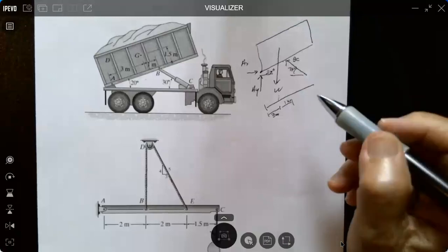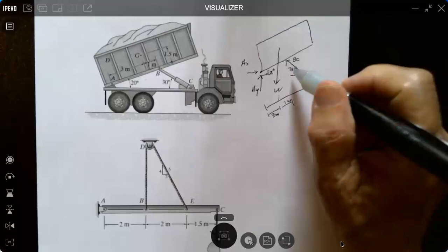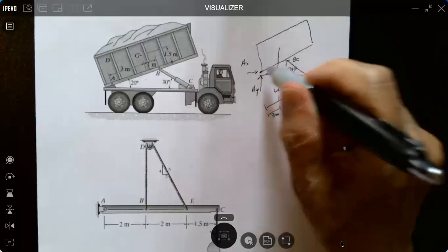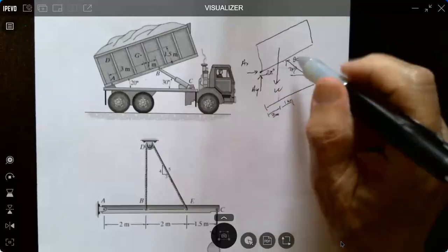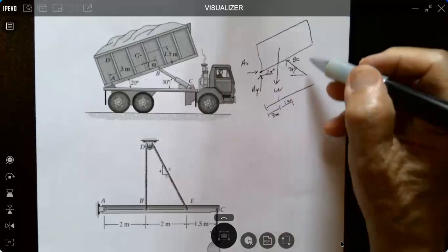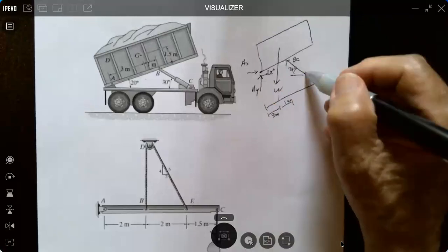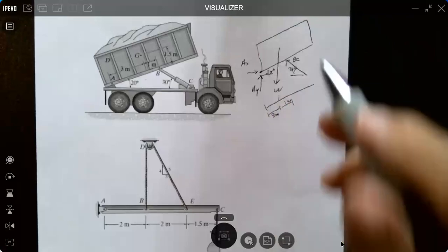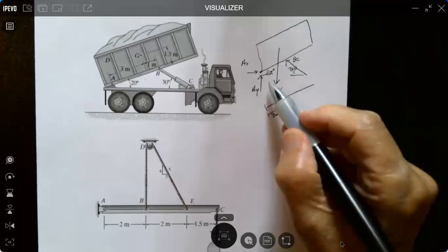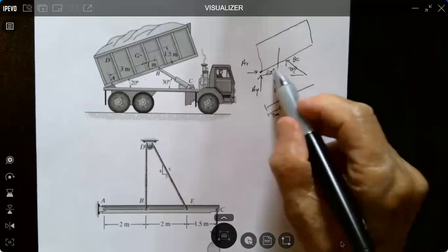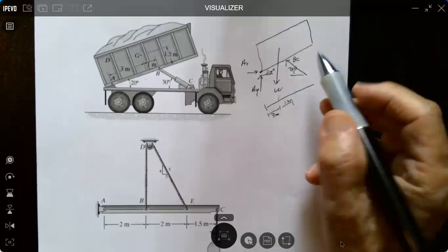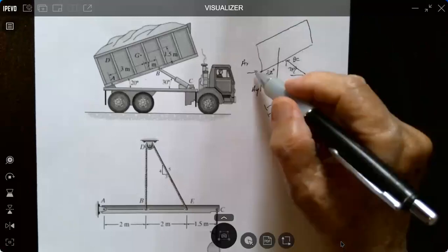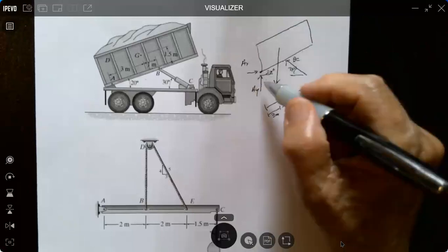And the solution, we've got 3 unknowns. So what I'm going to do is take moments about A, and I'm going to solve for BC. Okay, and I can do this a couple of different ways. I can get the X and Y components, and then I can get the X and Y dimensions, okay, the X dimension and so on. And we can solve for BC. And once we have BC, we can solve for A sub X, A sub Y using similar forces.